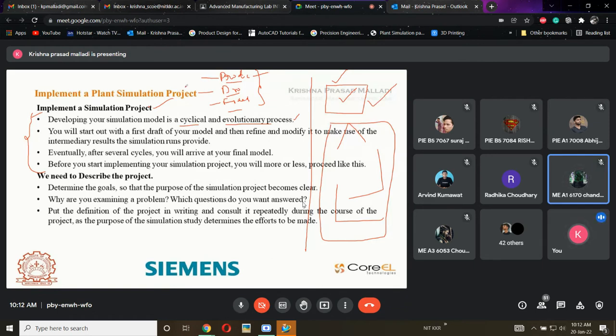Okay, I will explain it simply. In some conditions, product as well as process are similar. But if I want to differentiate, then product layout follows the product life cycle. Based upon the product movement, the line will be decided. So this is the product. If I want to move this product, then I will arrange the machines here. Based upon the product movement, the complete line will be defined. This is called a product layout, or line layout.